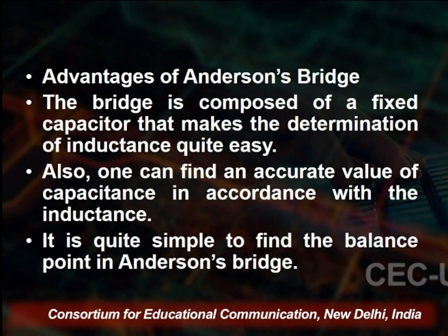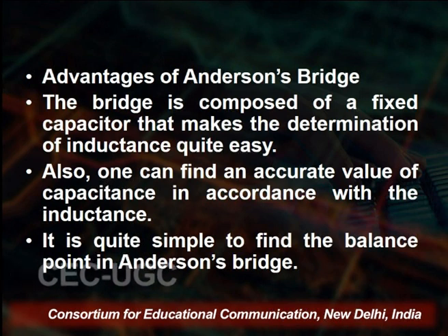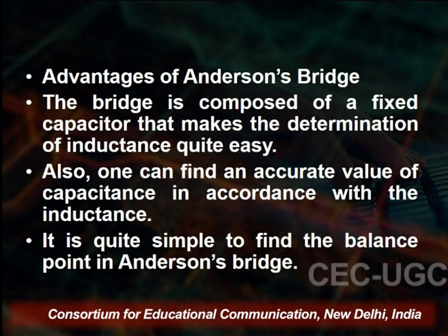So, what are the advantages of Anderson bridges? The bridge is composed of a fixed capacitor, that makes the determination of inductance quite easy. So, one can find the accurate value of the capacitance in accordance with the inductance by using the Anderson bridge. Another advantage is that it is quite simple to find out the balance point in the Anderson bridge.